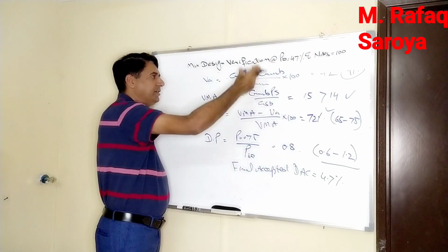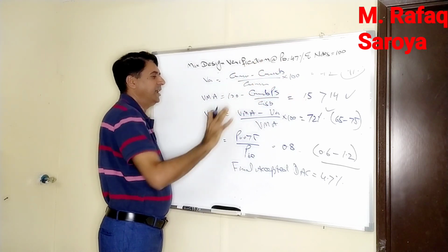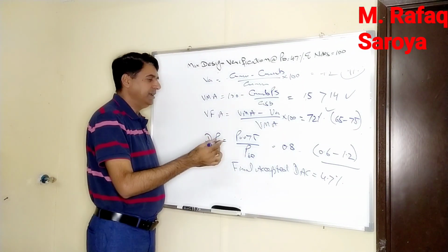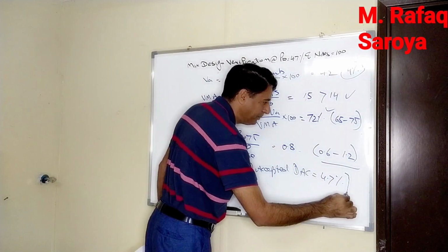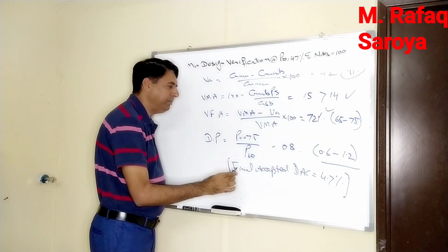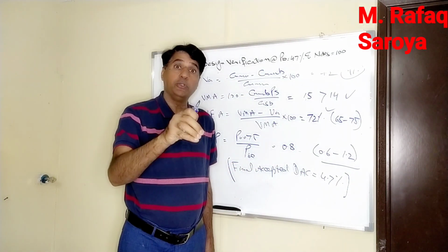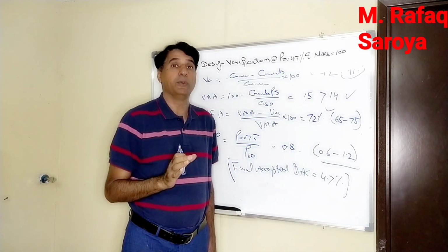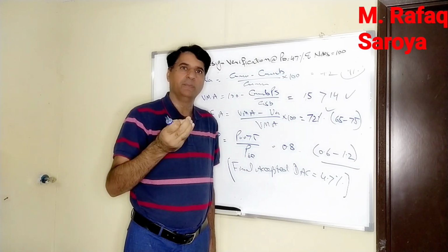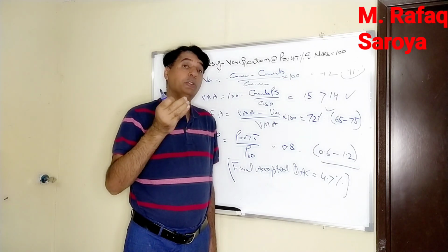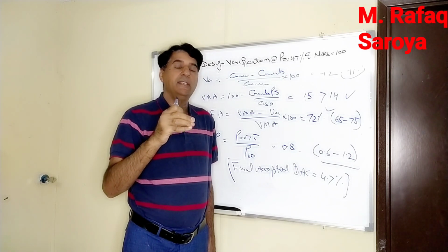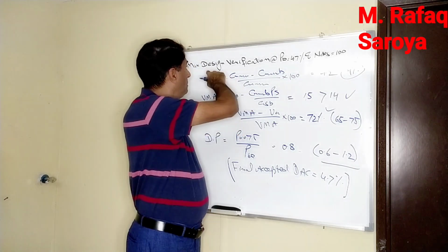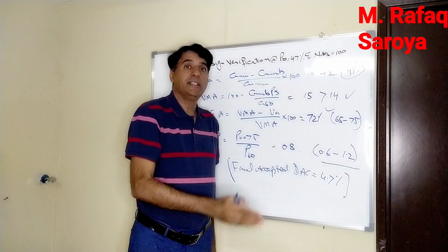And it is also checked by the mixing of the aggregate and the binder at this value. So that is why whenever we make the plant trial or whenever we make the material to be used at the site, we will use this amount of the binder, because it is our final accepted amount of the binder. So it was just an introduction: whenever you select your material as a design asphalt content, you have to verify it with that same amount, and this verification is done over here.